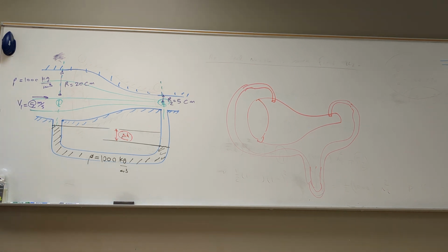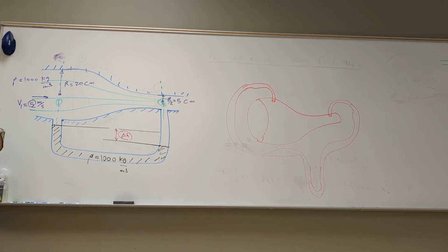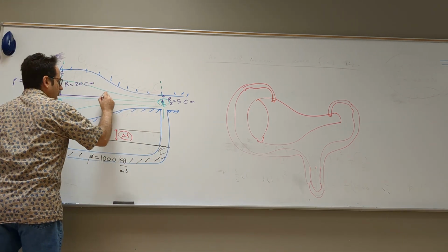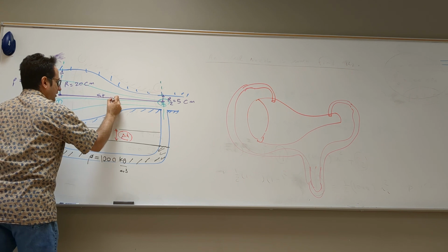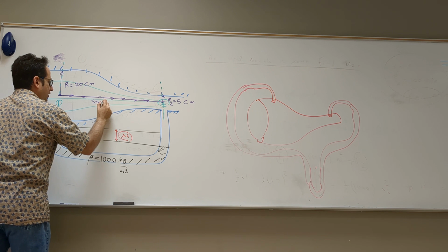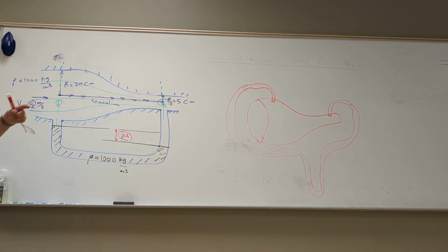Yeah, you can say that, but we're talking about pressure, not velocities. The pressure does not hold a relation with continuity. The continuity equation says if the cross-section area decreases, the velocity increases. But I'm talking about pressure, the delta P, the difference in pressure. If you take a streamline going from here to here, I know this is incompressible, the density is constant, and friction is very small.